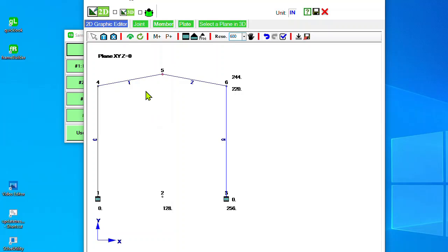Number 4, split each of the roof beams into 2 pieces. To connect 2 braces, we need to create joints on members 1 and 2, so that braces can be attached. The attaching point is located at the middle points of these 2 members. To do that, first, click the blue X button to clear all the tags. Then, use the arrow cursor to tag members 1 and 2.